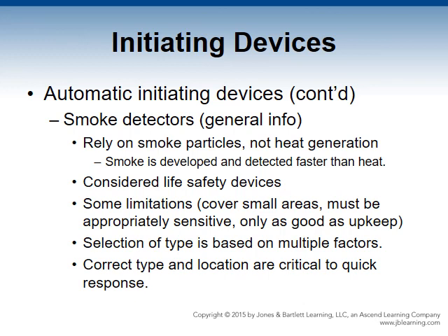Detector selection is based on a number of factors, such as environmental conditions, construction and design issues, building content, ceiling shape, height, and surface. Ventilation and airflow, and the burning characteristics of the combustible material may also affect them. The correct type and locations are critical to provide a quick response, ensuring life safety.